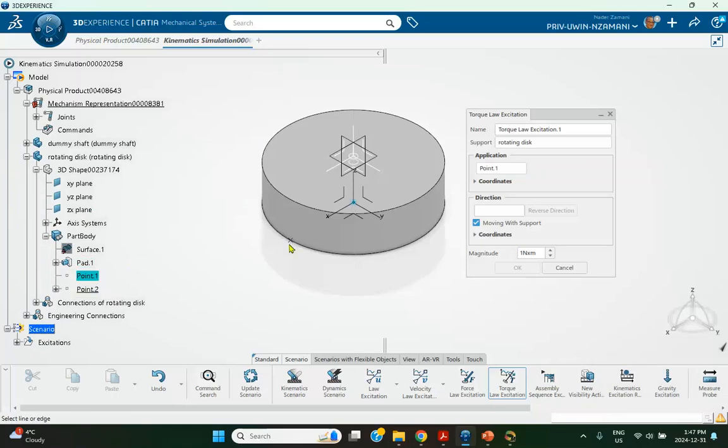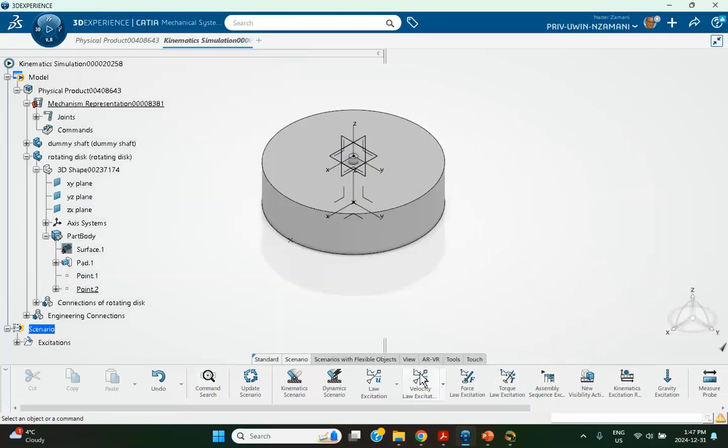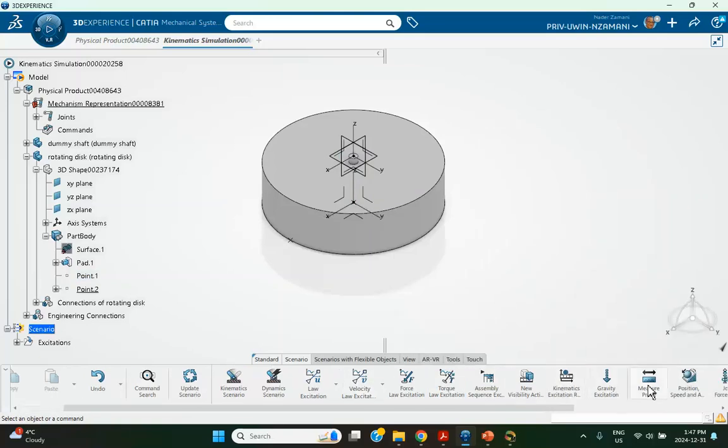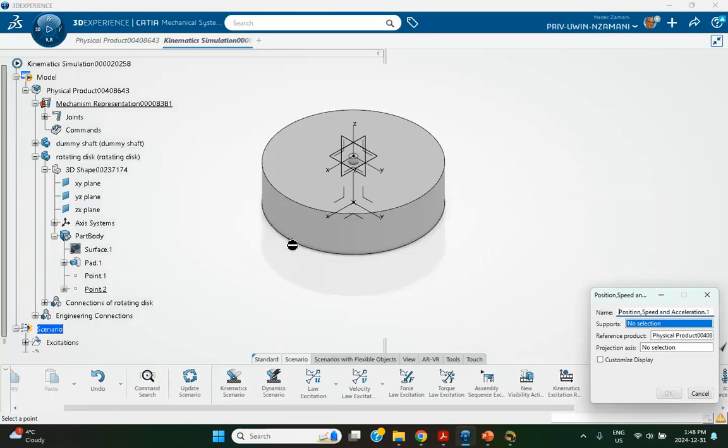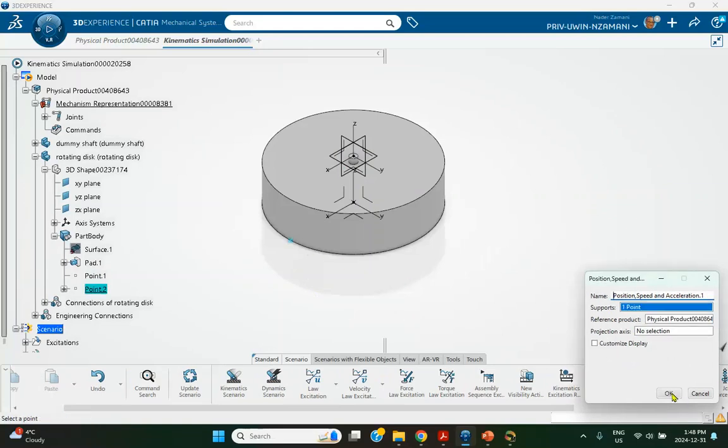Second one was for the probe. For the axis, I can select, for example, this Z axis or this axis. It doesn't really matter. And you put down here, I think I put down 10, right? 10. Good. So the probe, there's a probe here we're going to create at that location, if you want to monitor things at that location.